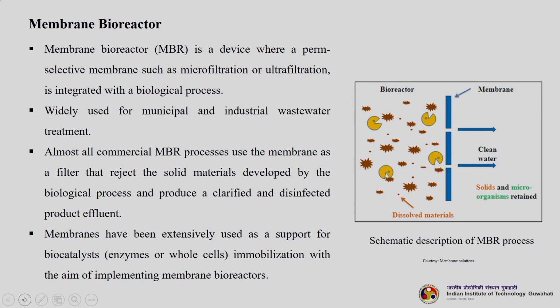Almost all commercial membrane bioreactor processes use the membrane as a filter that rejects the solid materials developed by the biological processes and produces a clarified and disinfected product effluent. Membranes have also been extensively used as a support for biocatalysts, that is, enzymes or whole cells immobilization, with the aim of implementing a membrane bioreactor. This is a schematic representation of the MBR process.